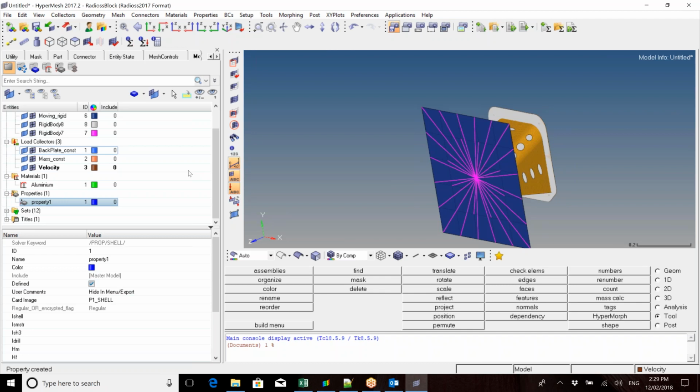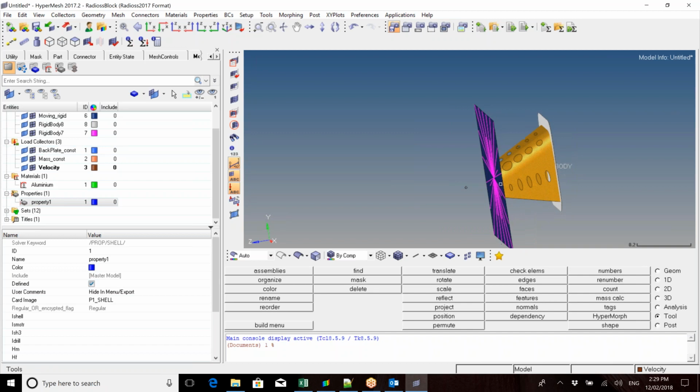If you need to use brick elements because you can't get away with them, definitely understand what you're doing with the solid meshing and understanding how to apply that correctly. But for this part, for the crash structure, we are only using shell elements because it's a mid-surfaced section, which I think we went through in the HyperMesh tutorial, which would have been the second proper webinar. It shows going through a mid-surface, and this is a section where we've used that. So definitely have a look, making sure you know what you're putting on.